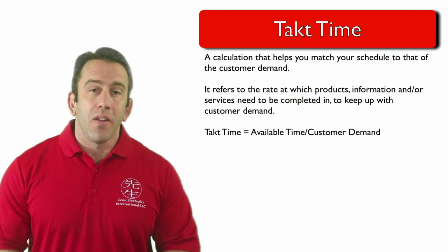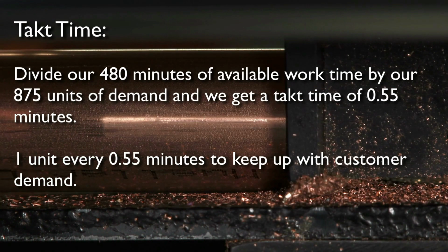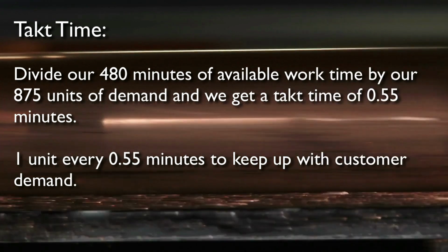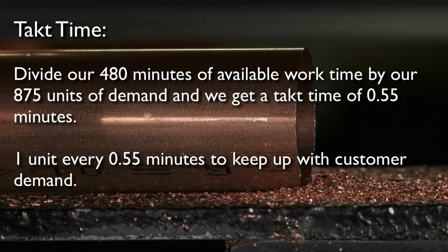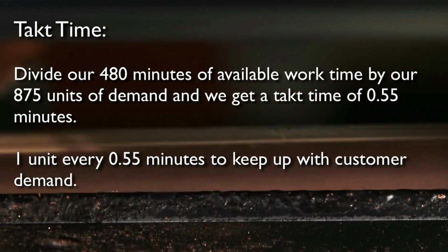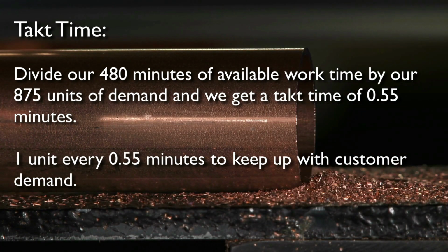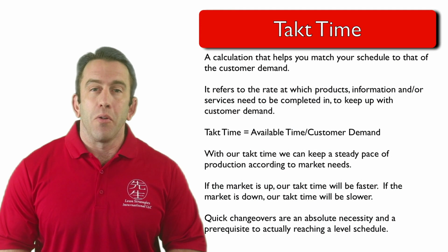Now we can calculate the takt time. To do this, we divide our 480 minutes of available work time by our 875 units of demand, and we get a takt time of 0.55 minutes. These are the minutes we need to produce. In other words, 1 unit every 0.55 minutes to keep up with customer demand.